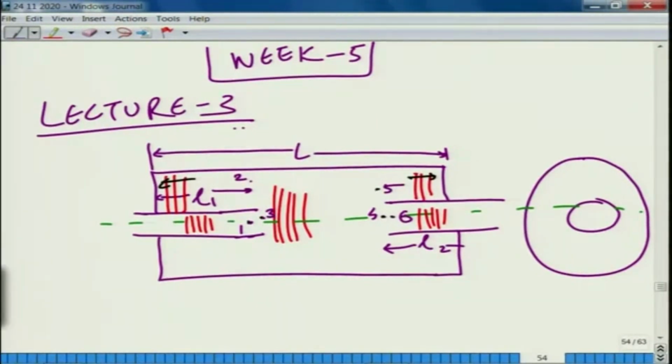The system is now well known to us. We have discussed it at length in the last lecture, lecture 2. So, in this lecture 3, our aim would be to derive the transfer matrix for the overall extended inlet and extended outlet system, and then use the derived transfer matrix between the inlet and outlet ports to obtain the transmission loss performance based on the planar wave propagation theory.